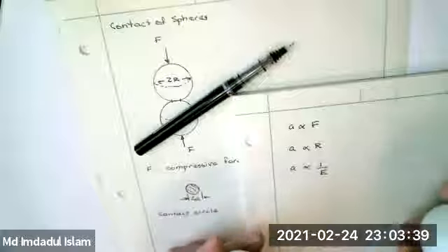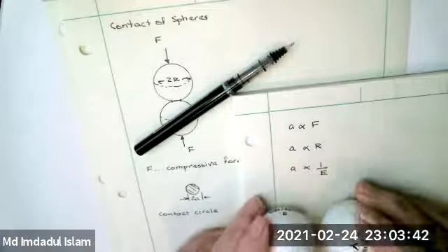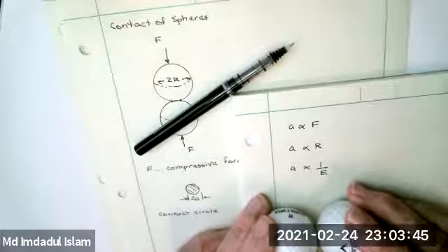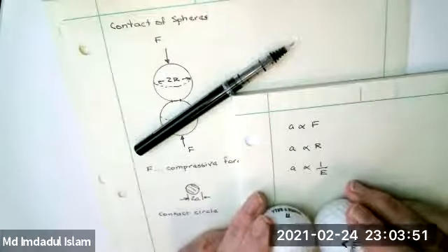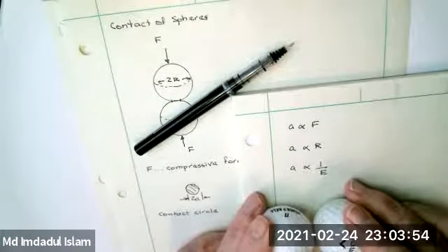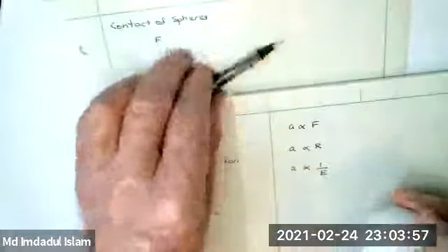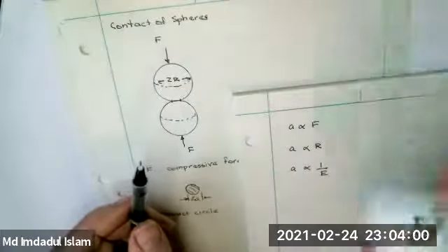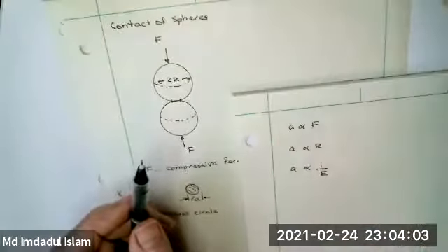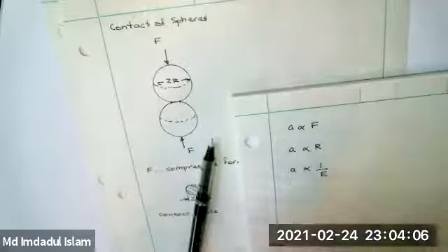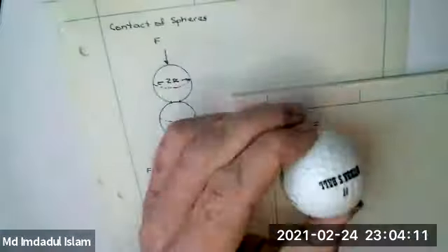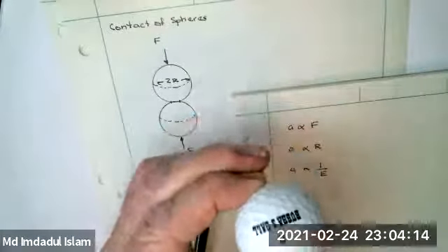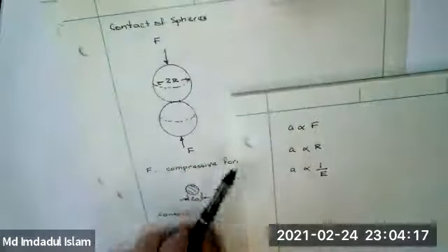It's much more. But with these demos, you can do these yourself at home and see the effects, if I'm not showing them that clearly on the computer. If you get 2 tennis balls and push them together, you get a much bigger contact region than if you push together 2 golf balls with the same force. One of the reasons for that is that these things are a lot stiffer. If I push this, I can make it give all the way. If I push the golf ball, my finger gives, but nothing else gives. And so this has got a much higher modulus in effect.